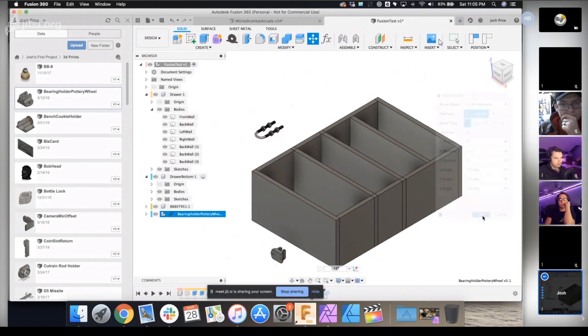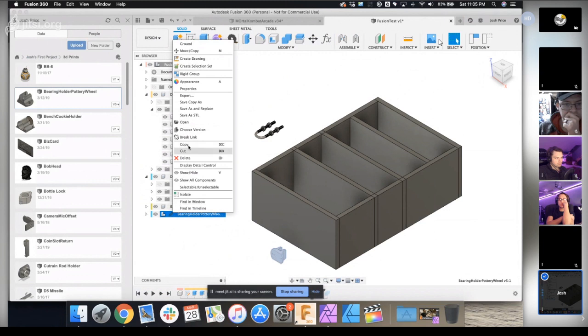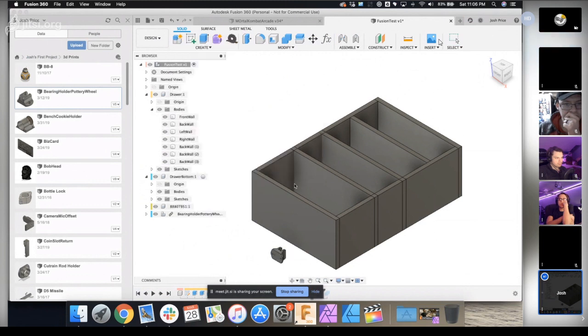You get your one free move, and as soon as you hit OK, because it has that little link right there, if, say, a person who's working on the kitchen island updates something, it will update into your current entire kitchen model, which also means that if you try to move this little guy in your kitchen model, it will move over here too. If you don't want that, if you just want to use your project library as a repository for models, you can import it, and then you can just break the link. And then you can move it all day. Okay. So very good for collaboration. But if you move it into the thing you dropped it into, it's also going to move it over here and vice versa.